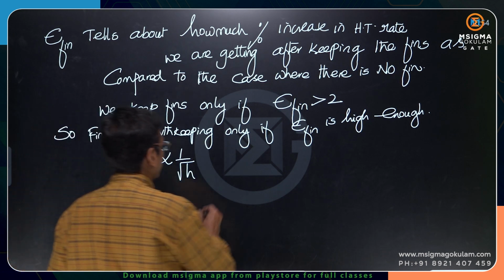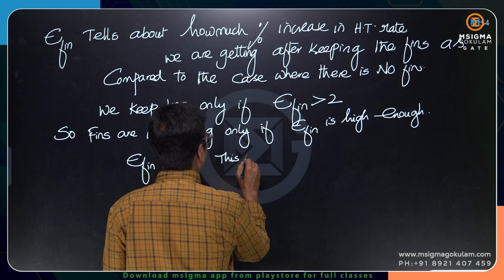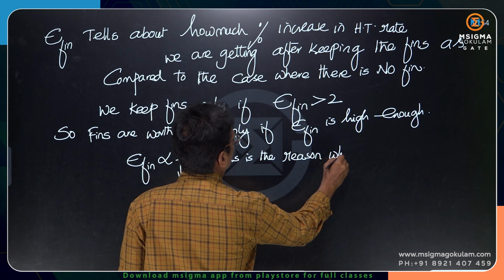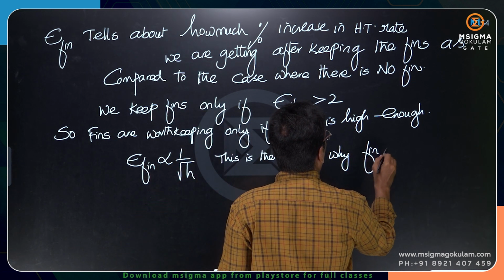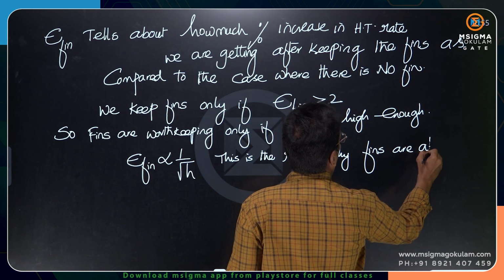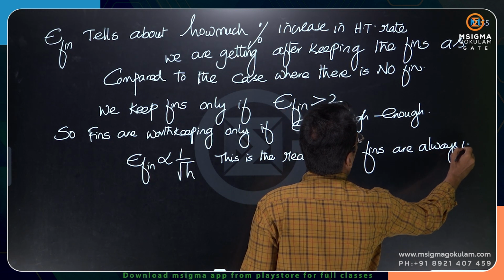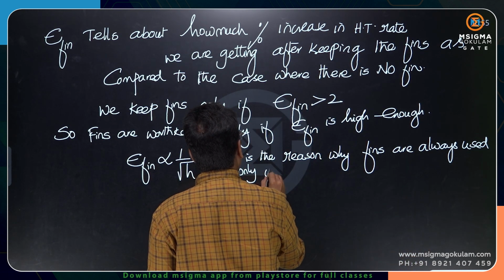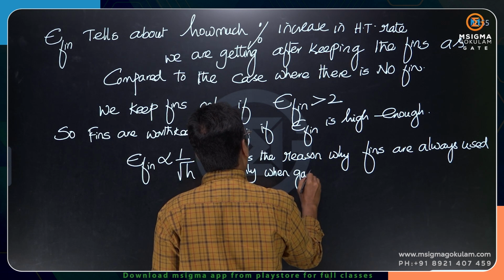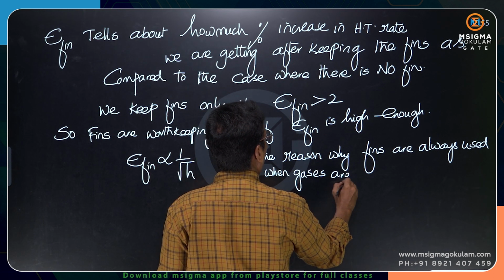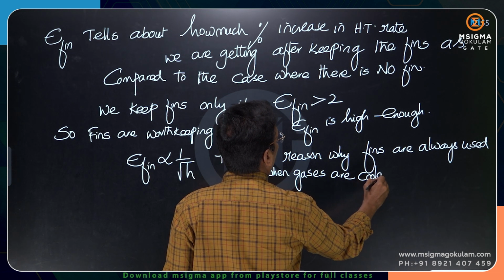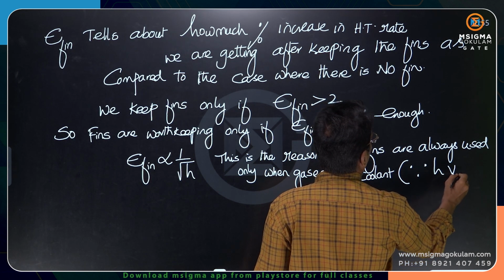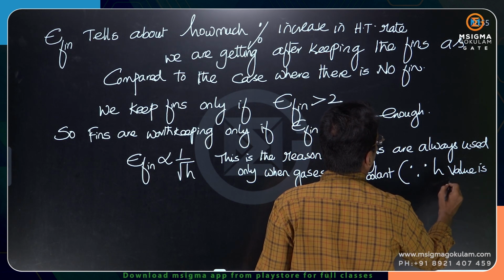So this is the reason why fins are always used with gases, are always used only when gases are coolant, since h value is low with gases.